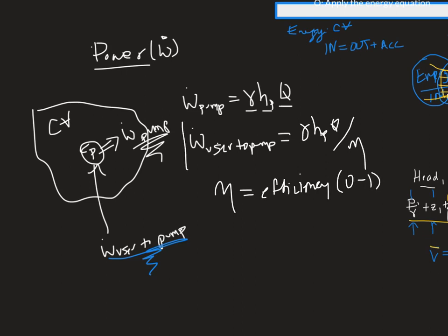So I never remember this formula, okay? I can never remember it. And the way I do it is I say to myself, okay, the pump serves out 100 kilowatts. I'm going to need to supply more than 100. So do I multiply or divide by the efficiency in order to get how much I need to supply? Okay, and that's how I do it. Because in a second, I'm going to change all this, but I'm going to do it for a turbine. Okay, so we're going to change this to a turbine.